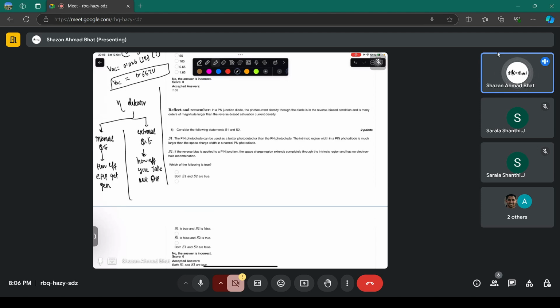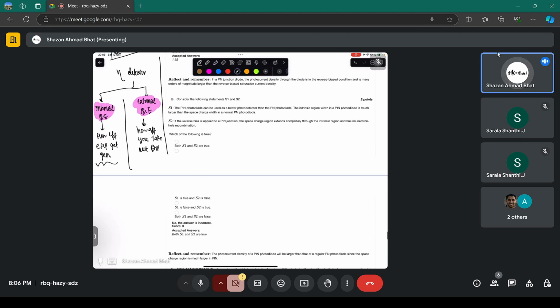Okay, these are the two efficiencies which are mostly confused in the literature, even in the books. So this is the internal thing of a detector. It's a material characteristic. External quantum efficiency is also a material characteristic, but it depends upon how efficiently you are extracting those electron hole pairs.